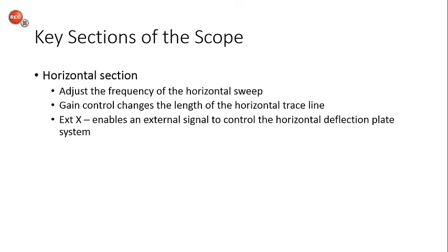There's also an external connection that enables an external signal to control the horizontal deflection plate system. And so again, by default, we apply a sawtooth wave there, but we could apply other waveforms to the horizontal plates as well if we desired.